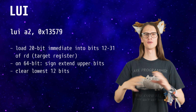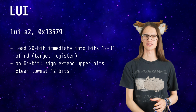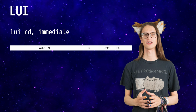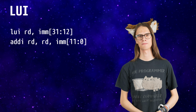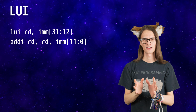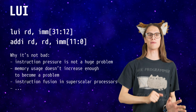Instead of loading the full 32-bit value in one go, what if we instead loaded the upper part of it with this LUI instruction? The encoding reserves 20 bits of space for an immediate. Then we add the remaining lower 12 bits onto this value by means of an add immediate instruction. Every 32-bit immediate load becomes 2 instructions. But more instructions does not automatically mean more bad in RISC land. In fact, it almost never means more bad.